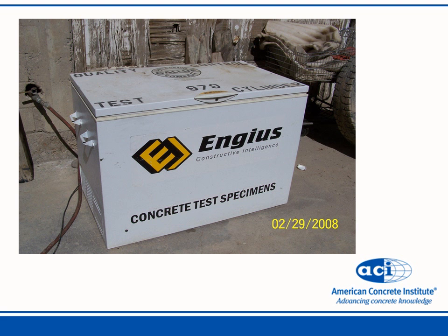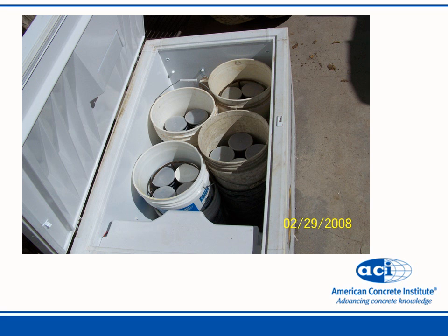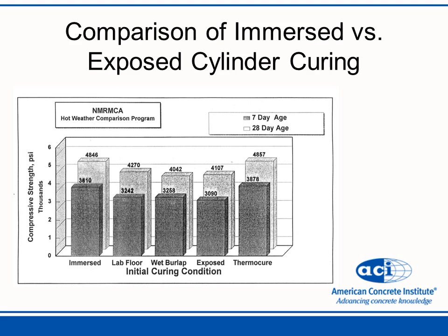Another box was for test specimens. This one looked like a freezer, and we would put in 8 5-gallon buckets, each with 4 cylinders, and each bucket was filled with water. The cylinders were placed in this cooler, and this cooler again was another method of keeping the water bath in the cylinders between 60 and 80 degrees, and this was done at a job site. This tends to be a dry box, as I would call it.